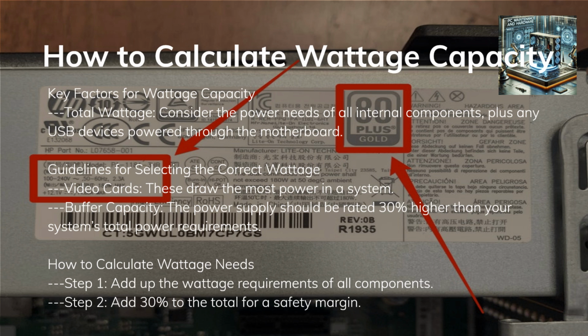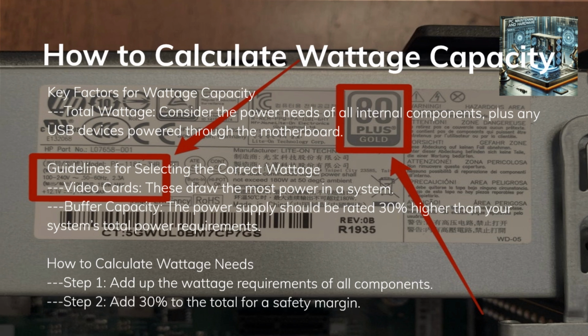Video cards are typically the most power-hungry component, and your power supply should be rated about 30% higher than your system's total power requirements. To figure out the right wattage, simply add up the wattage of all your components, then add an additional 30% for safety.